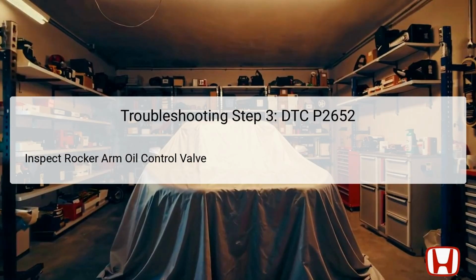This valve plays an essential role in managing the oil flow to the rocker arms based on the engine's operational needs. Begin this process by ensuring that any previous tests on the sensor circuit have confirmed normal conditions. If so, it is likely that the rocker arm oil control valve itself is malfunctioning. Inspect the valve for any clogs or mechanical issues that could interfere with oil flow.